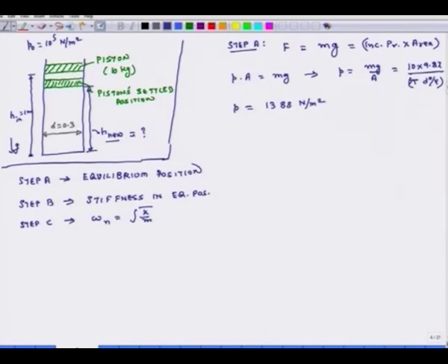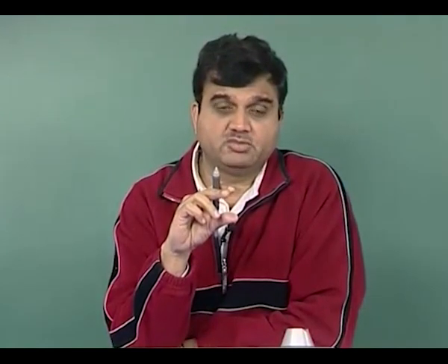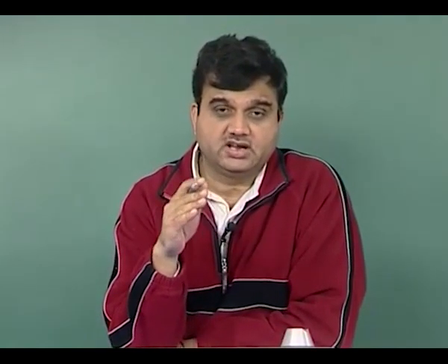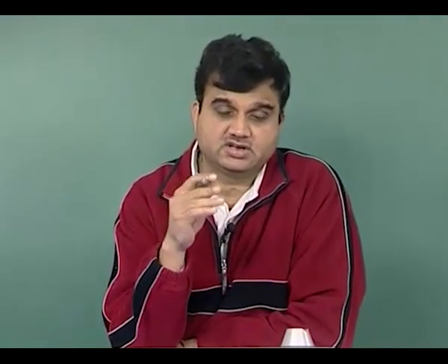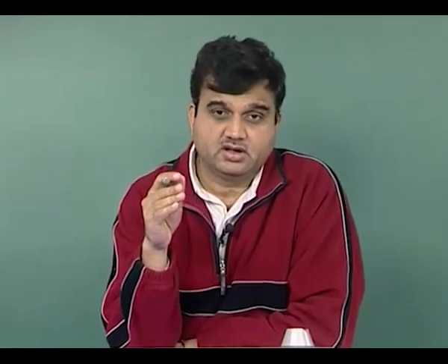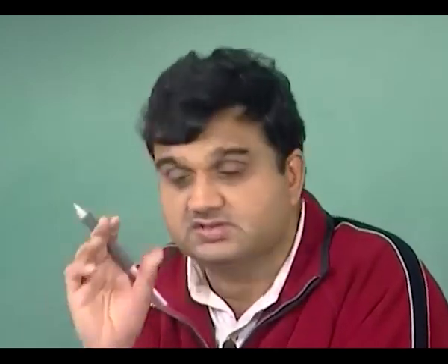Now, we know that this piston is settling slowly, and what that means in thermodynamic terms is that all the extra heat, as this air is getting compressed, is able to get out, and the temperature of air outside the cylinder and inside the cylinder has to remain the same. So, the overall temperature of the cylinder does not change. So, this is an isothermal process.